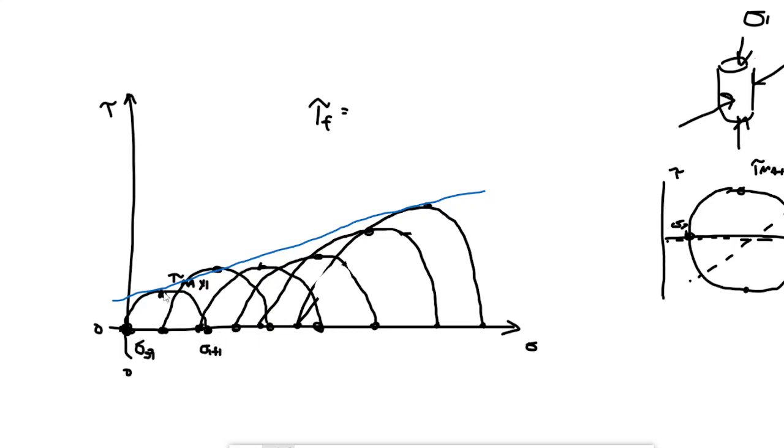So what's usually going to be easiest for us is to just take each of these tau maxes, which is sitting directly above on the Mohr's circle. I'll draw it on this one that actually looks like a nice circle. If you draw this down, what you see is, again, it's that sigma sub m, or sigma mean. The mean value of the stresses is where tau max is going to occur.